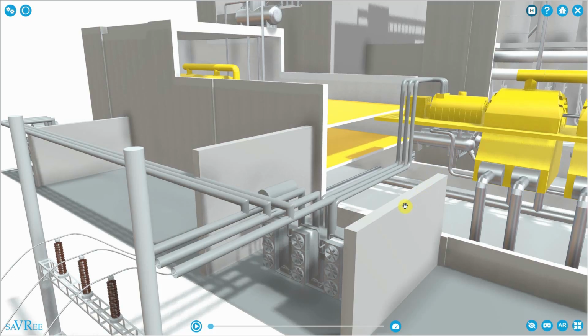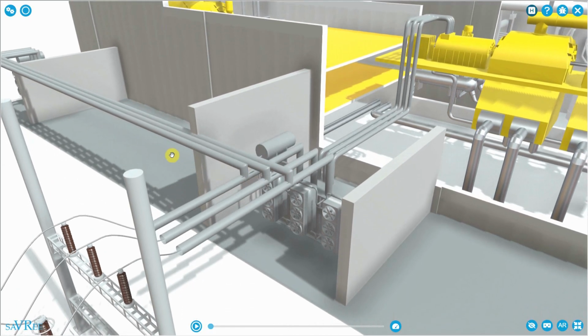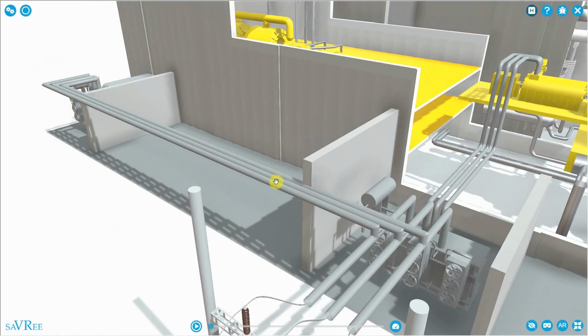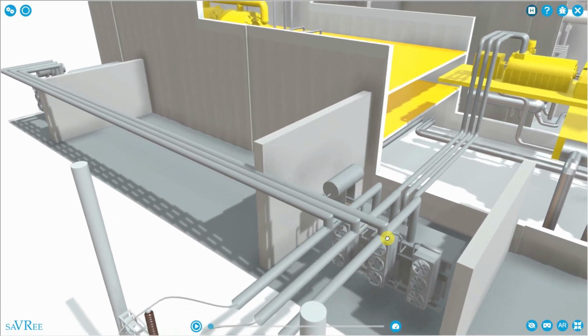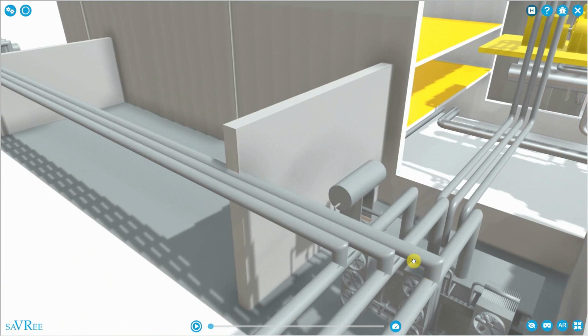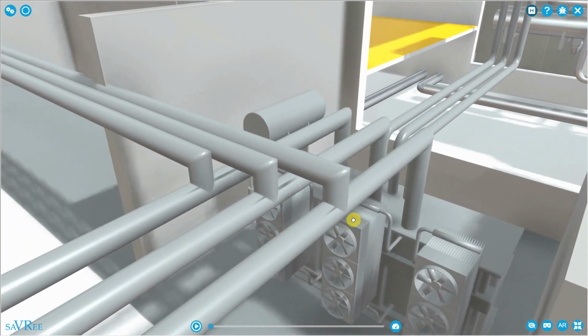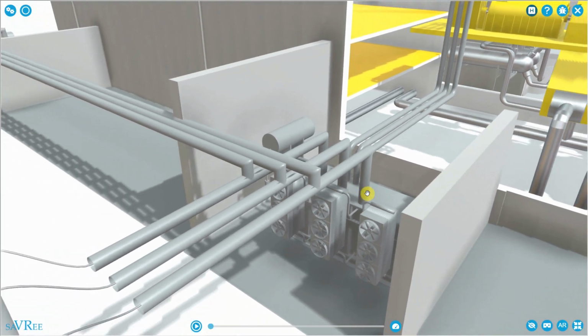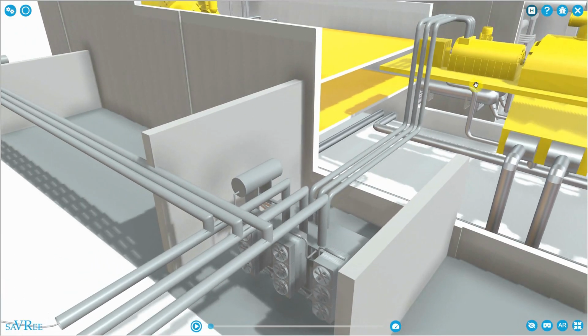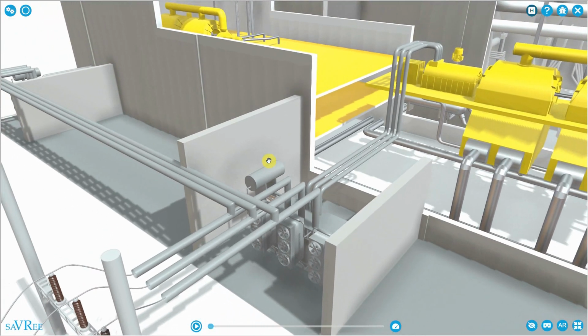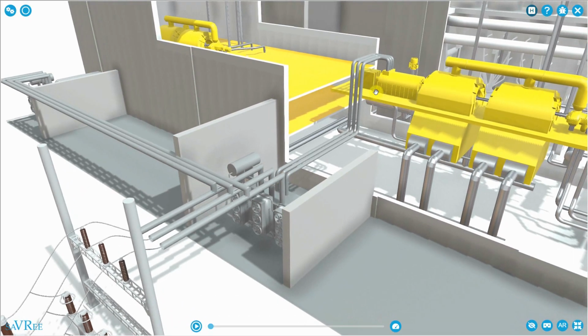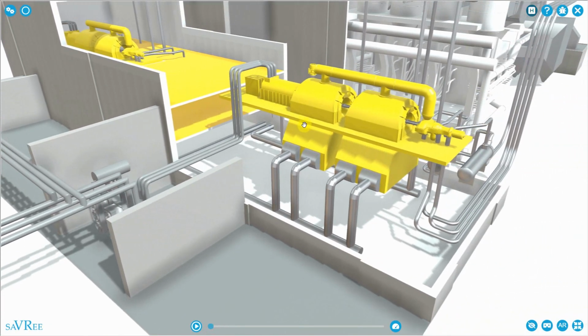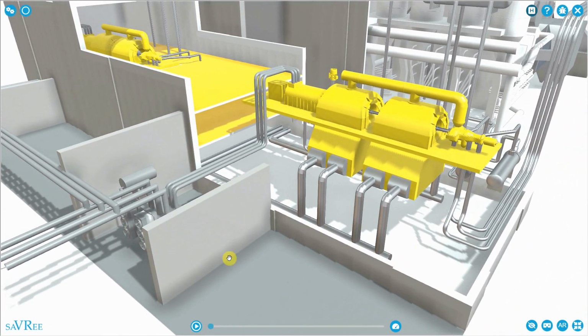I just want to mention here that this arrangement, where a transformer feeds along here and onto the same bus as another transformer, is quite unusual. This would not usually occur. The electrical transformers and the generators will usually be fully independent. There's a good reason for this. If a generator or a transformer should fail, then it might mean that our entire steam turbine is out of action and we can't generate power from all of this equipment within this area.